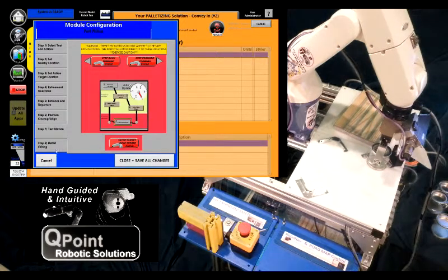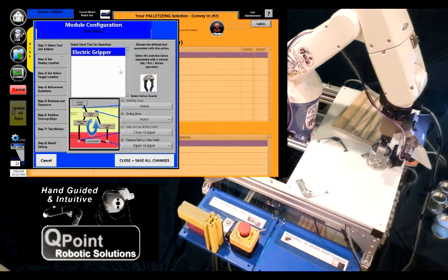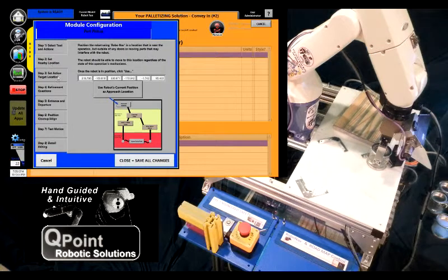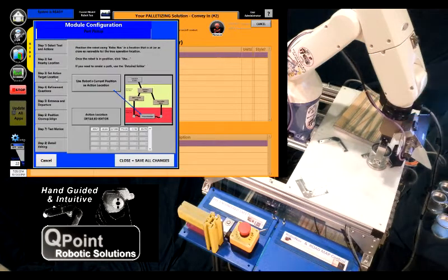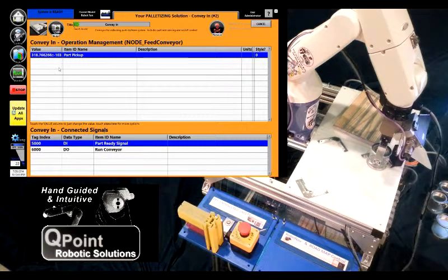So we can test the motion and just say, hey, we're all set. So really it was just picking which tool we're using. You get a nearby location that's out in a safe region. You get the actual action point on it. And then you just hit the easy button twice and you're done. So now we have taught that pickup location.